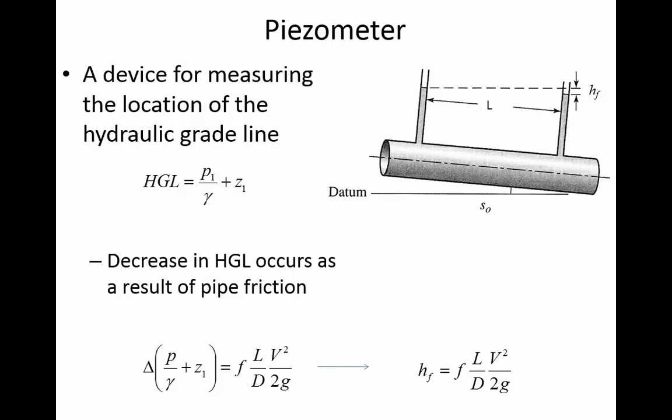Diameter of the pipe is in the denominator, meaning that if you have a small pipe, what effect is that going to have on the energy loss? It's going to have a lot of energy loss, actually for 2 reasons. A smaller pipe is going to increase the velocity, so that's the indirect effect of the small pipe. But directly, when you have a small pipe, think about how far away you are from where the resistance is.